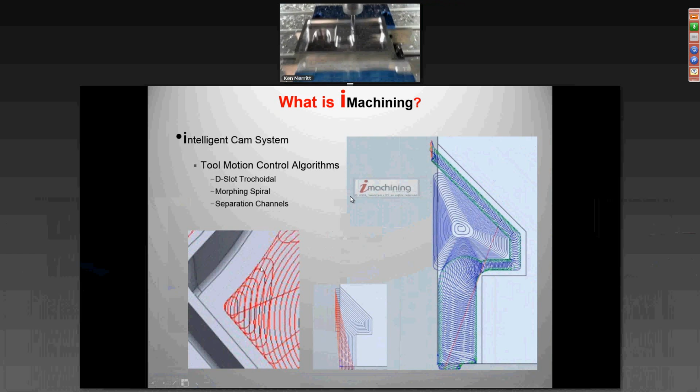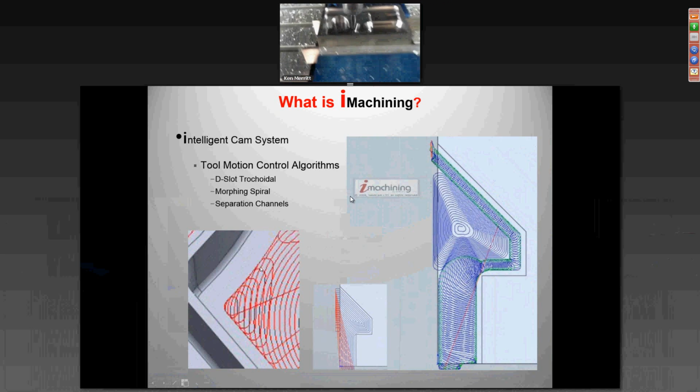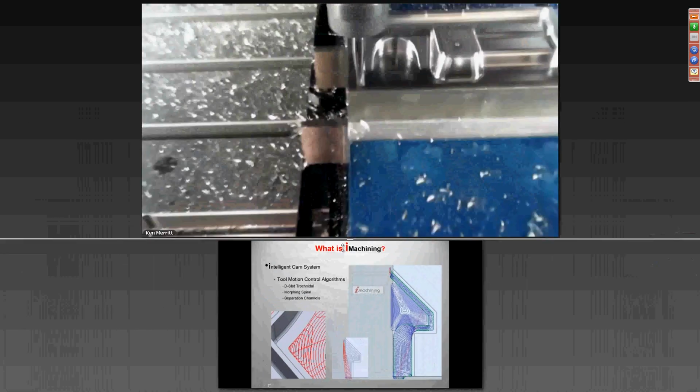And hey, just a quickie, let me point you over to the camera inside the machine right now. That's an 1/8" ball tool, guys. We're doing the final clean out in the rest material down in the bottom of these pockets, the little bitty fillets in there. This is running at 16,000 RPM and 160 inches a minute, dry in steel with an 1/8" 2-flute ball. And you're going to be amazed at what you see for a surface finish in there. It's crazy. Also, I wish you could feel this machine. This thing is dead smooth right now. Even running that fast and changing direction as rapidly as it is, the machine is running extremely smooth. Very, very nice. So I just wanted to point that out because we're getting close to the end of this cut here. Anyway, back to what we're talking about.